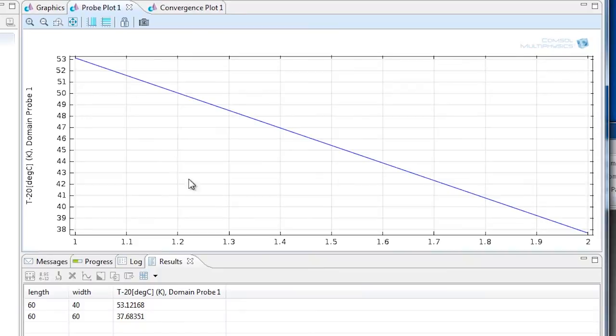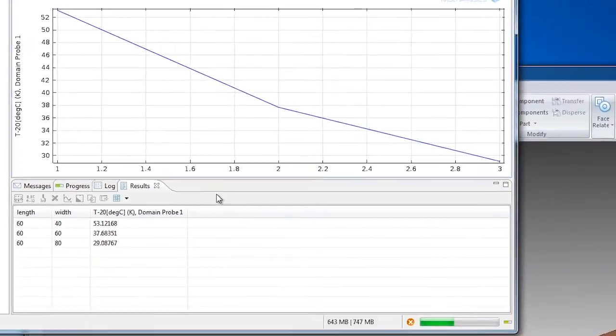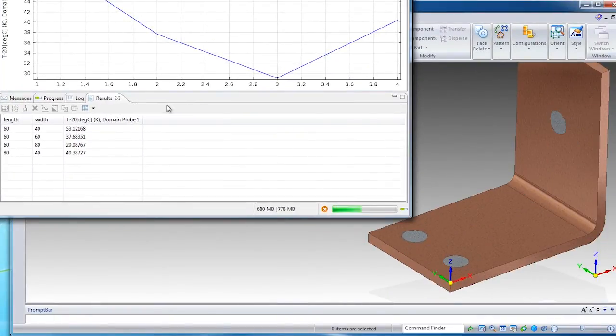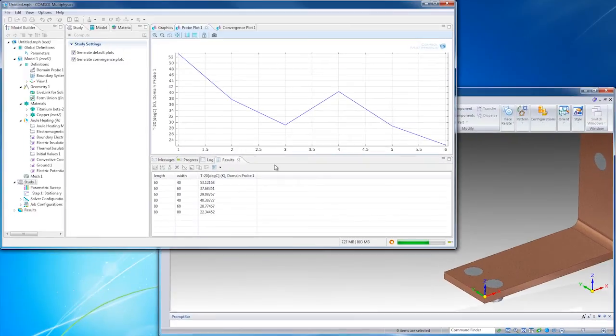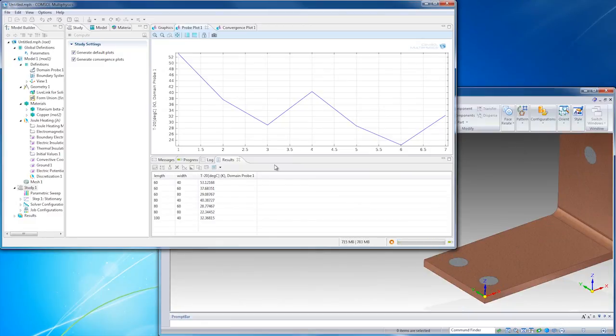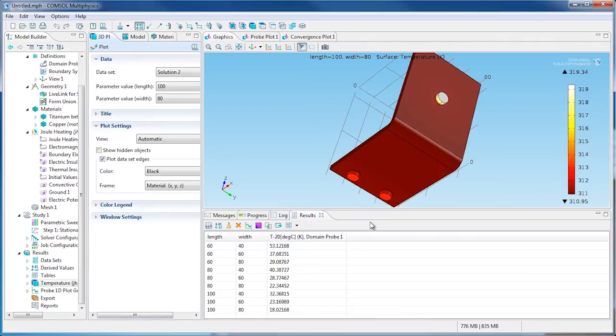I can follow this process in a plot. For each new parameter combination, the values are synchronized with SolidEdge, where the geometry is rebuilt and synchronized to COMSOL. Back in COMSOL, the sweep is almost done, and I can see how the temperature increase lowers for the larger dimensions of the bus bar.